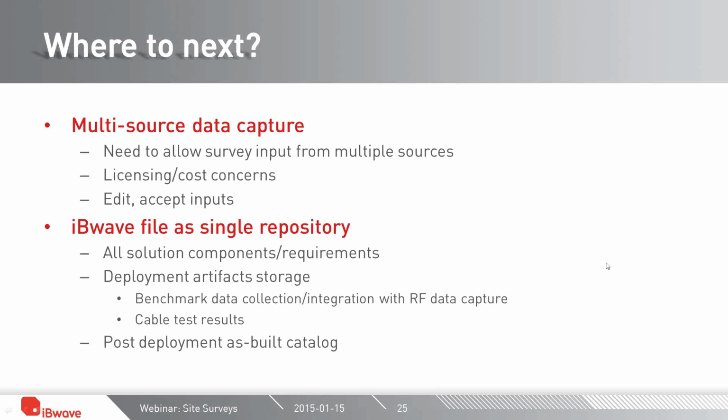And then beyond that, the ability to use iBwave as a singular repository for all the design artifacts. I'm talking beyond what we've mentioned at this point, but iBwave is working on things like pulling in benchmark data directly from those devices. I see things along the lines of cable testing data from the cable test process, getting that pulled in there. So all of that lives with the design file as opposed to being scattered across the corporate network and potentially lost. And the goal would be to build that as-built catalog out of the design file itself, inclusive of all those components.